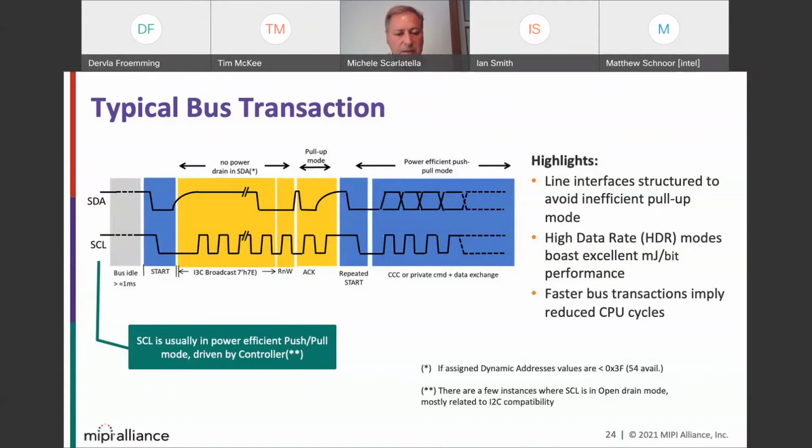The other thing is that in that part of the transaction, the bus can be arbitrated, meaning another device can pull the line low and try to gain the bus. So with a smart selection of addresses, there are chunks of address space you can assign, and there is a nice set where the first bit is 0. If nobody is claiming, meaning nobody will arbitrate, you can go into a fast clock mode for the rest of the bits.